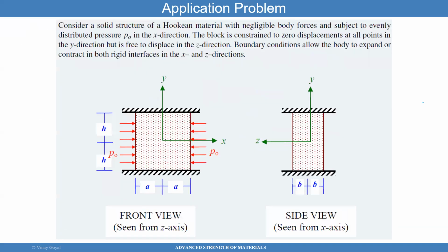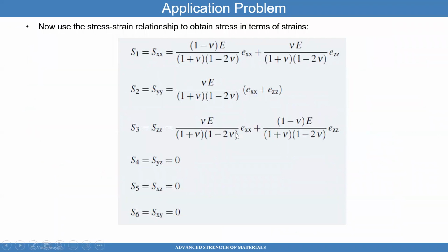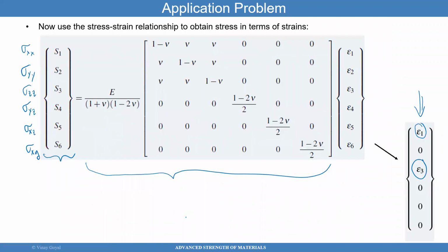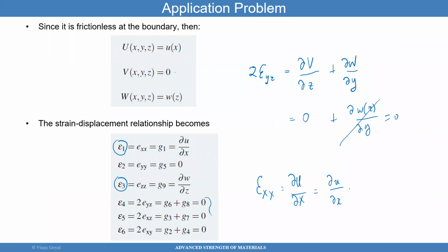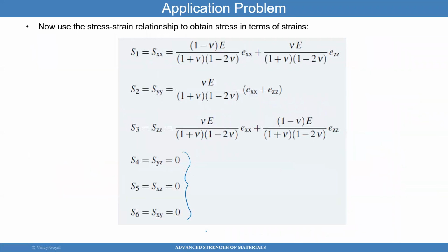If I apply a compression load to this surface and this surface uniformly, and I have a square here, I don't expect the square to distort for an isotropic material. It doesn't seem to make sense. It's unlikely that this square is going to experience an angle change, given the loading environments I have. So that makes sense. I'm getting that the shear stresses are 0 and that the shear strains are 0. That makes a lot of sense.